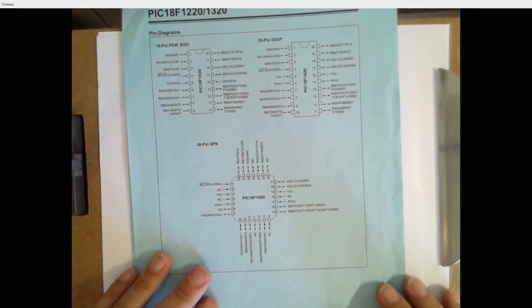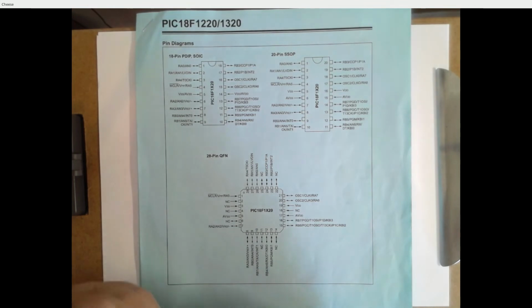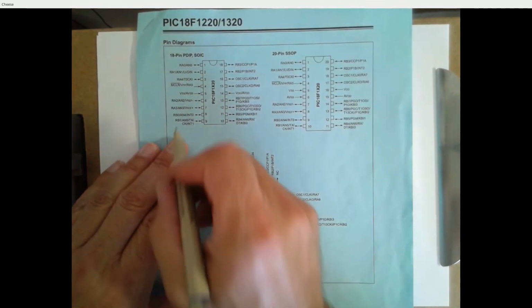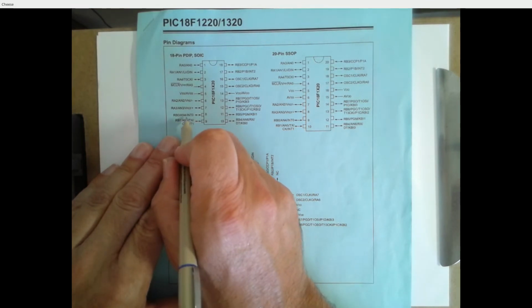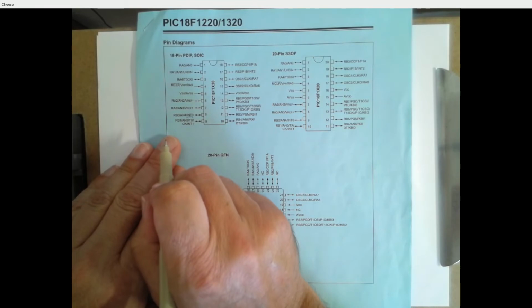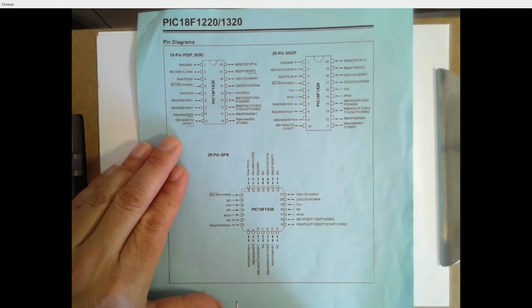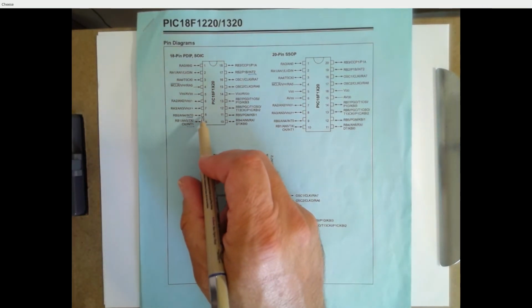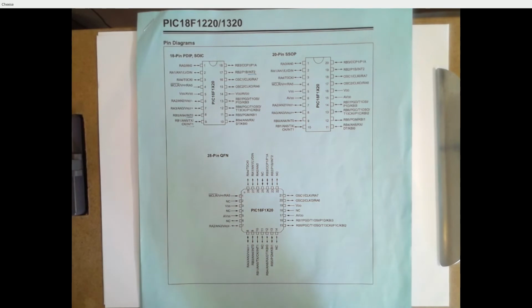And we're going to deal with one particular type of interrupt for now, but there's a lot of other types, and some of these we'll talk about later. But this is a hardware interrupt triggered by raising the voltage on pin 8. So pin 8 has this function of INT0, interrupt 0. Pin 9 is INT1, pin 17 is INT2. We can hook a switch up to pin 8, for example, and normally put in 0 volts, but arrange things in software so that if we put 5 volts into here, it will generate an interrupt.